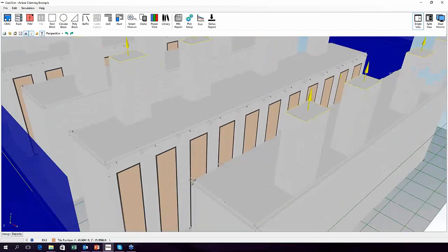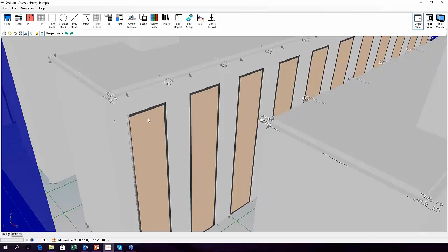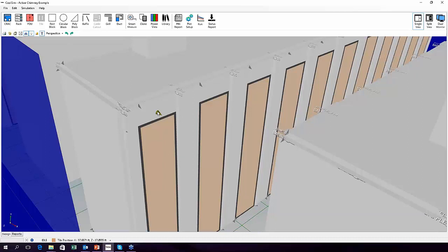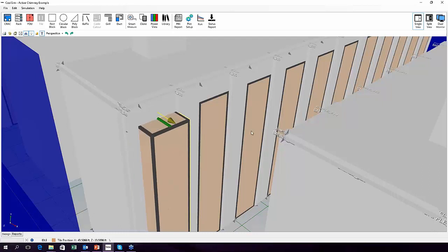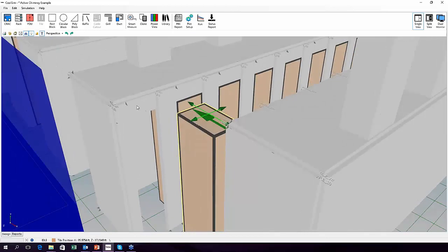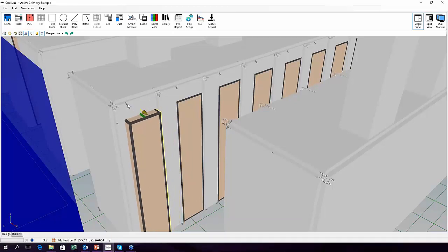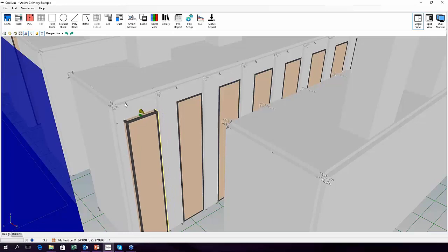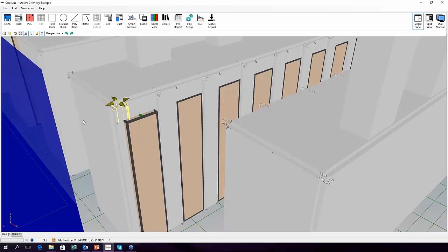The way that racks work is, again, as long as the front is popping through the block or the baffle, it'll run. So here, I'm just going to grab this and pull it. You see me pulling it through. As long as that front is poking through, then it's going to be fine. Now, in this case, whoever did it put the specific detail around it. You don't need to do that. It'll actually slice through just like that, as long as the inlet and outlet are there and showing. So you can build them like this, and you can set your rack rail leakage to whatever you want using baffles. Baffles allow leakage, so let's see what the rack rail leakage here was at 5%.